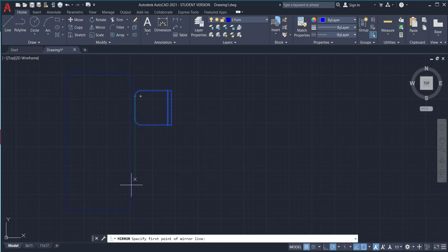I want it to be centered down here, and I can do that because I know that this one is centered up here. So all I have to do is find the center of the table because my O-snap midpoint is checked. I'm going to click and draw a line, and you can see how it ghosts a chair. No matter where I put my line, it makes a copy and it places it exactly the same distance away from the mirror as the previous chair was.